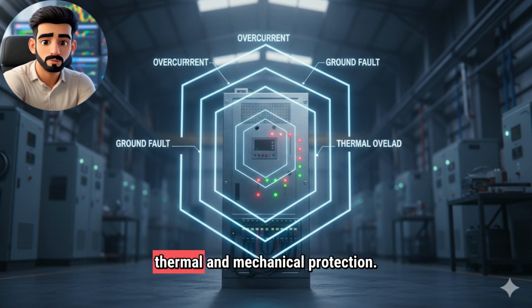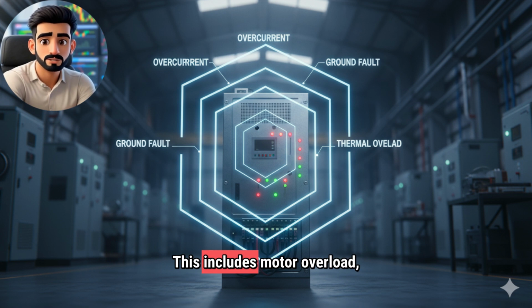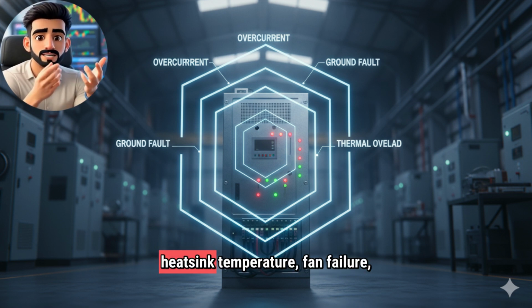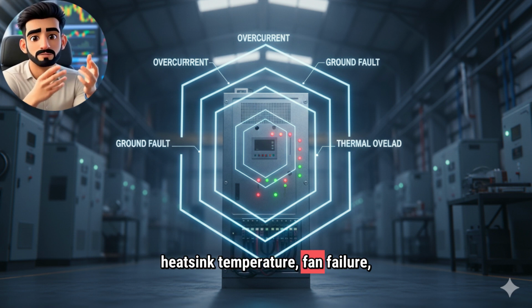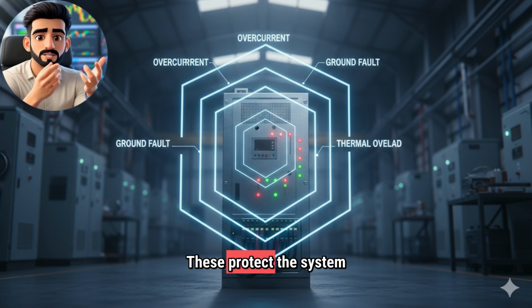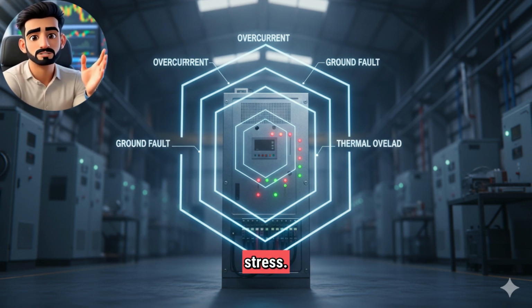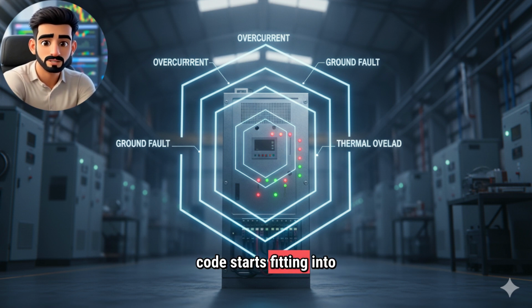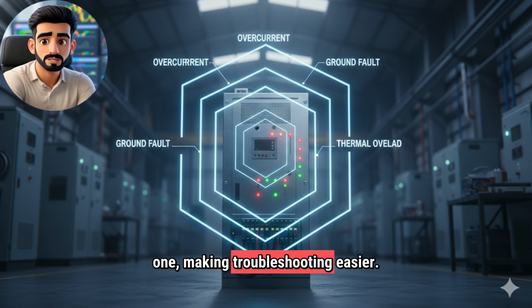The second level is thermal and mechanical protection. This includes motor overload, motor thermal model, drive heat sink temperature, fan failure, ambient temperature, and stall prevention features. These protect the system from thermal and mechanical stress. Once you understand these two categories, every fault code starts fitting into one, making troubleshooting easier.